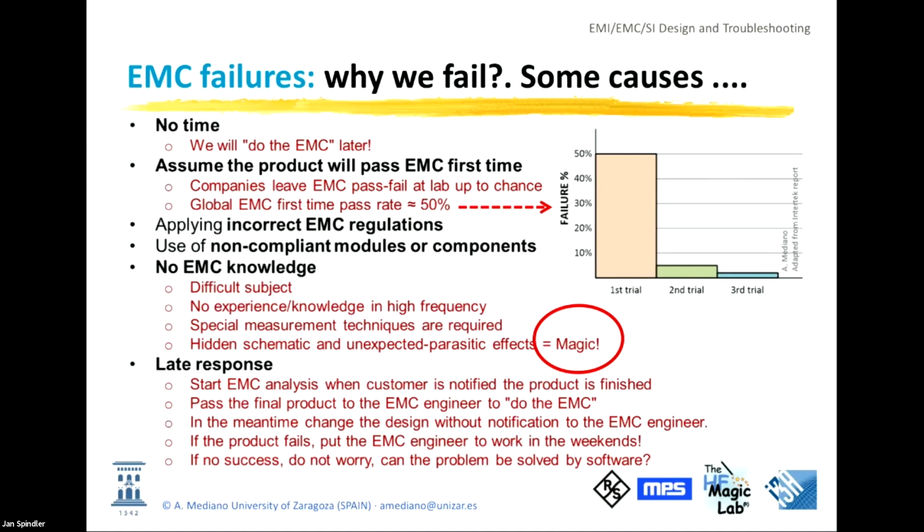Another important idea, late response. I am sure that you know about these ideas. For example, we start the EMC analysis when the customer knows that the product is close to being finished. This is a very big mistake. You need to solve problems and the customer is waiting for the product. Second, pass the final product to the EMC engineer, he will solve the problem. In the meantime, while the EMC designer is solving the problem, you make changes in the mechanical design, in the cables. And additionally, you don't tell him that you are making the changes.